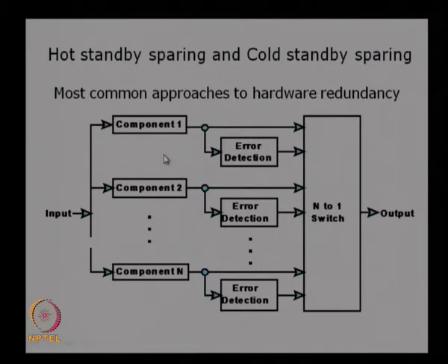In a system where we cannot have a delay in outputs, or it is very critical and you cannot have a stoppage of output even for a short duration, in such situations we need to go for hot standby. You can compare it with a system where we have a UPS supplying power to a computer. Most of the time, your UPS also will be in a ready mode to supply power.